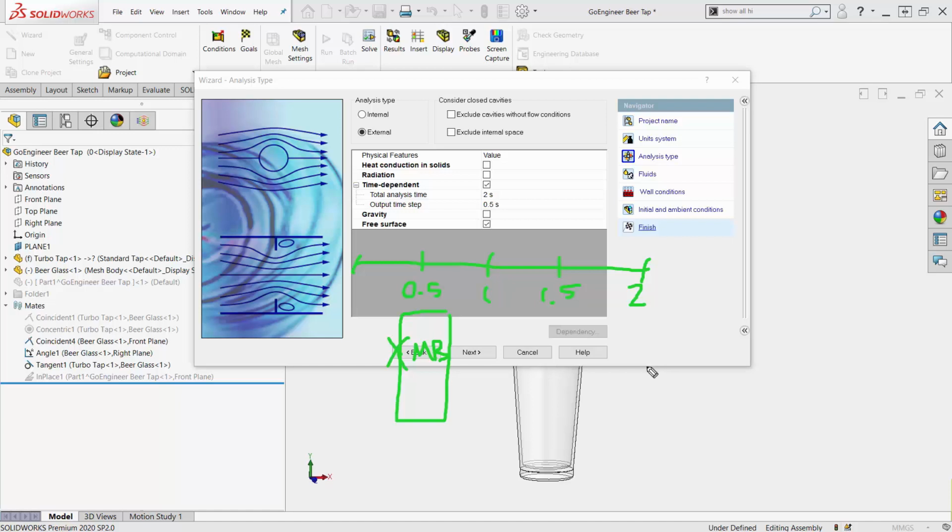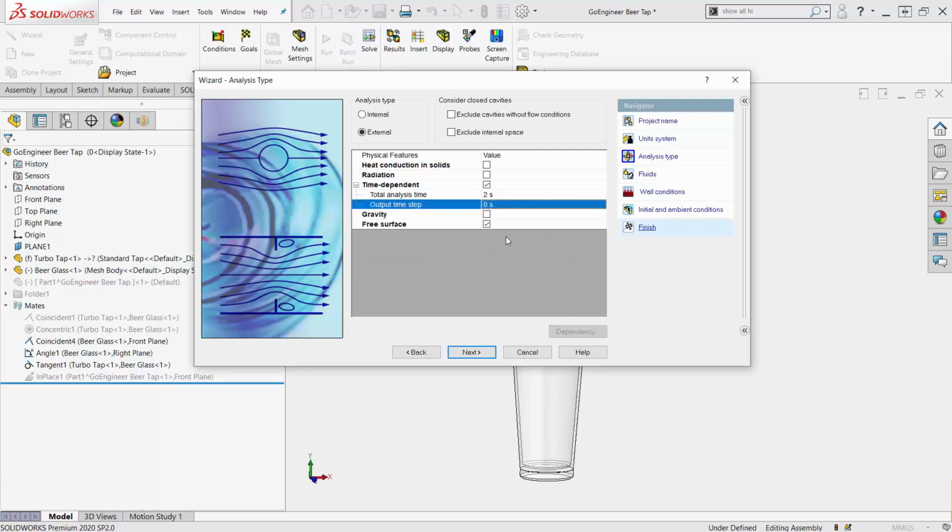So what do I truly need out of this analysis? I want to know how the nucleation sites are created over time, and I'm curious what the final result looks like. So I don't necessarily need specific time steps like this to be able to get a look at the nucleation sites. I recommend, and this is a Shivaniism, this is a me thing, having that not create individual outputs for particular time steps for this kind of setup, for this scenario.